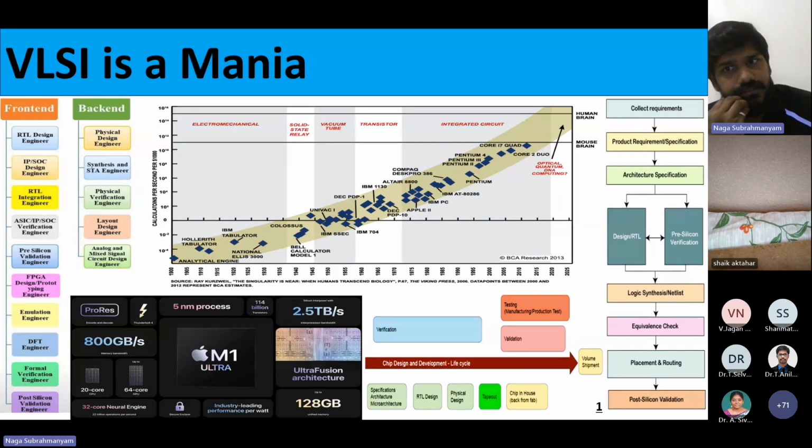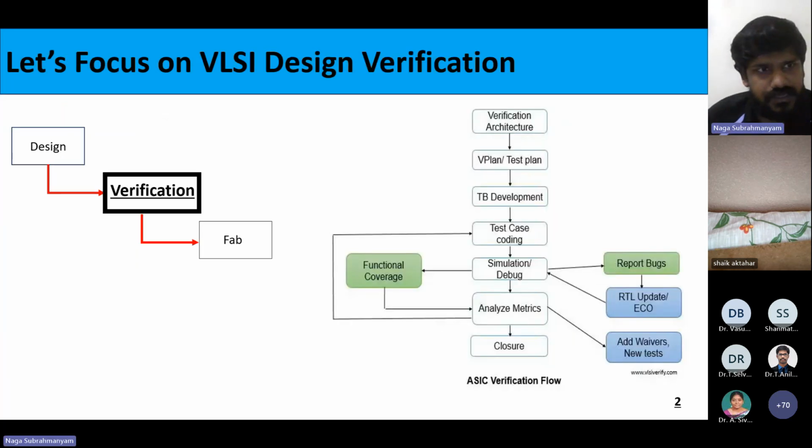After that we will verify the required features only. I'll come to what kind of features. After that, if we find any bugs, we will report those bugs. According to that they'll change the RTL and release again. Again we will apply all the plans we previously verified. So like that it will go hand in hand. So this is the thing in brief.